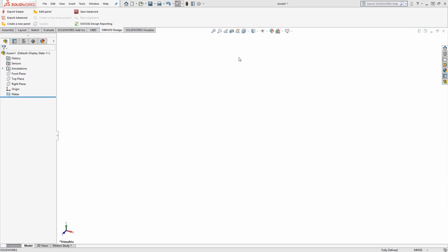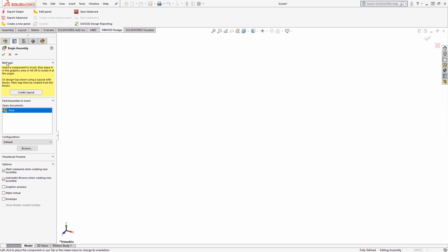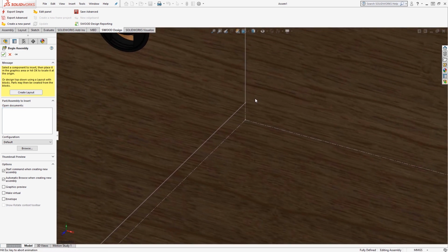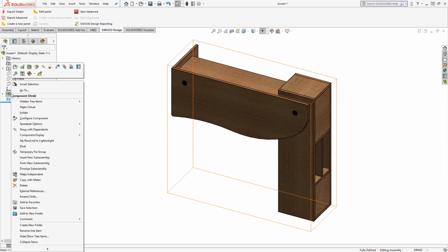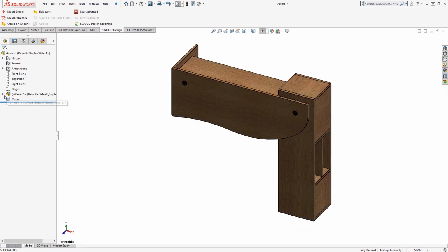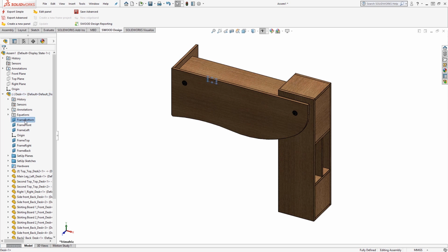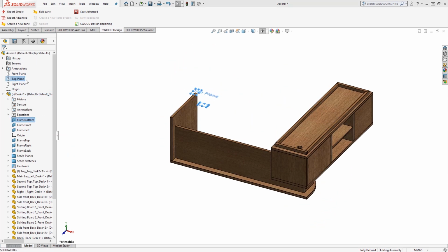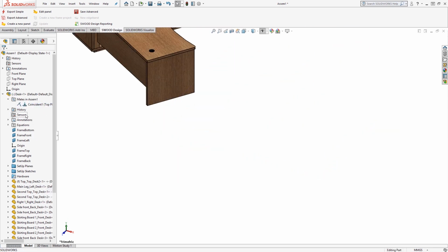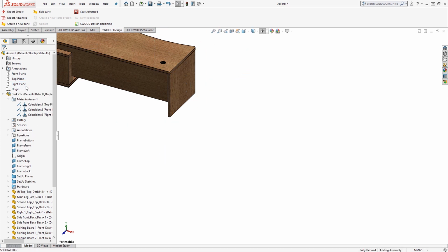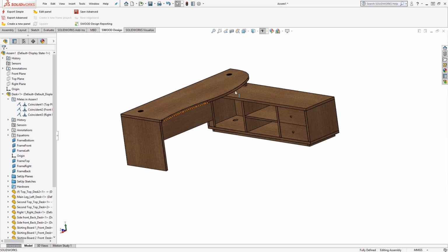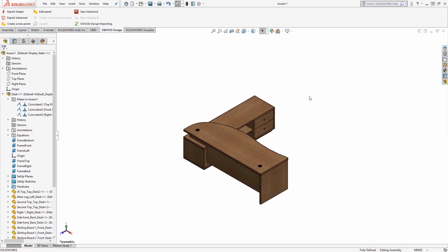Once you have done this, the best thing to do is to take the project into New Assembly, ready to take into Visualize. Although not strictly necessary, this allows you to reorientate the model and make sure the top level assembly's top plane is parallel with the bottom plane of the model. Depending on how you modelled it, it may be at an angle such as this desk. Although you can rotate this in Visualize, you don't have mates like you do in SOLIDWORKS. You only have values that you can change, and therefore it is easier to sort out in SOLIDWORKS before bringing the file into Visualize. Another benefit of this is you can add extra models into this file that are only needed for the render and not actually needed for manufacture.